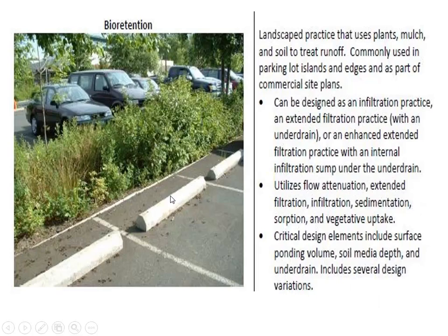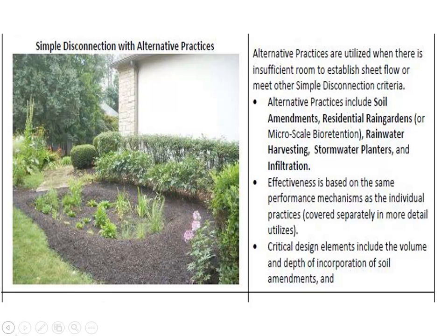If you modify the soil and maybe put gravel underneath this bed of plants, and make other modifications to improve the infiltration capacity of the soil, then you can have improved performance. Also, the plants will evapotranspirate water. So in addition to allowing infiltration, they'll promote the evaporation of water.